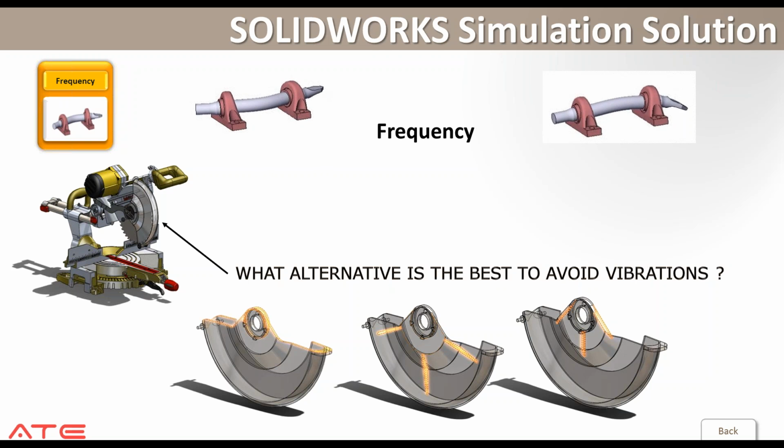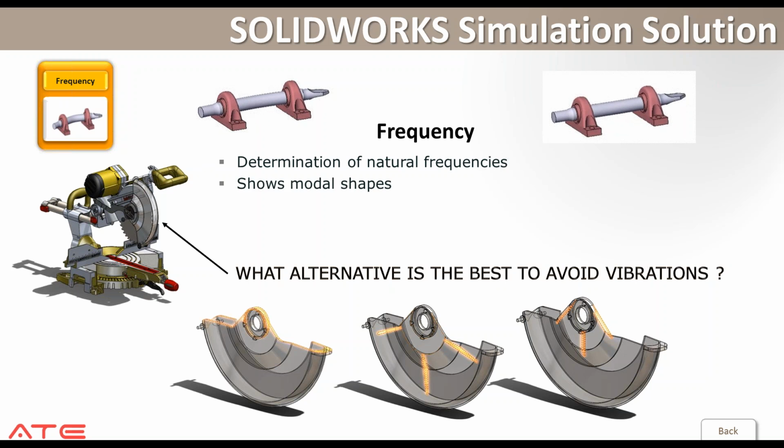So frequency tests are typically important when we are calculating on moving components or components which are attached to one particular motor, or in seismic earthquake scenarios. So frequencies can be very fatal. It can be very fatal when the natural frequencies or the resonance are being met. So we can calculate for different modes, different mode shapes, and plan how to avoid these particular vibrations by adding ribs such as in the bottoms.